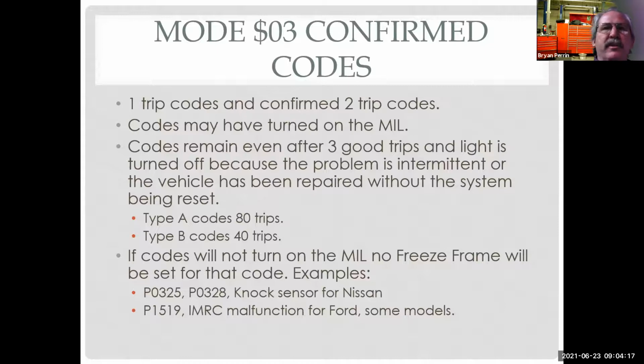So it won't let you get into timing check mode with a NOx sensor code. So you're not fixing the code because the light's on, you're fixing the code because you can't check timing, and you can't pass smog unless you can check timing. On the 4 cylinders, the V6s will let you check it.